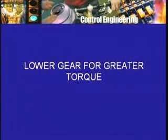So one may install such a mechanism so that starting from as high a speed as 1500, I may be able to get lower speeds by shifting into a lower gear. And of course, because my motor can still produce 5 kilowatts, if the speed is lower, then I can produce a higher torque. And this is exactly why you change gears when riding a scooter or an automobile.